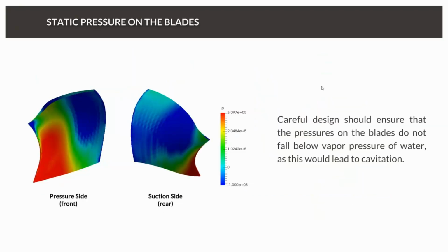The other important thing, I think, is longevity and the lifetime of our design. And here basically we're looking at two things. This is a single blade, looking at the front and the rear. So on the left we have the front of the blade, and on the right we have the back, right? It's like a plane wing essentially, and the right-hand side, which is the rear of the blade, is the top of the wing. So that's basically where the flow has to go the fastest. And we have a lower pressure, and that sucks the blade around in a circular motion.